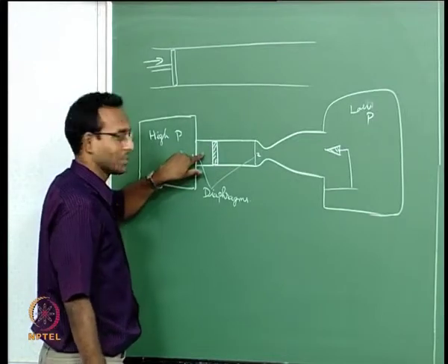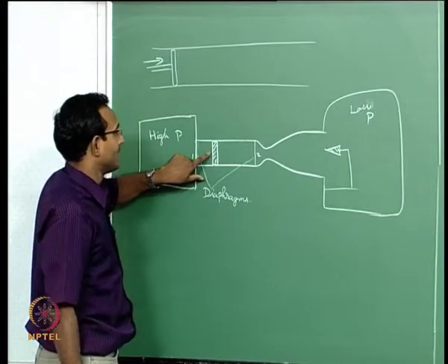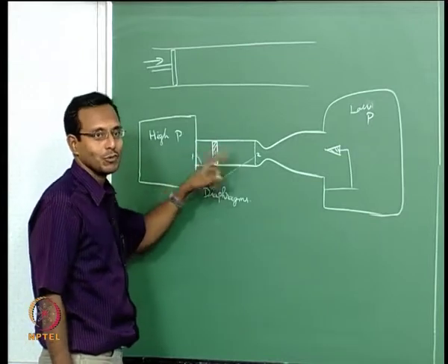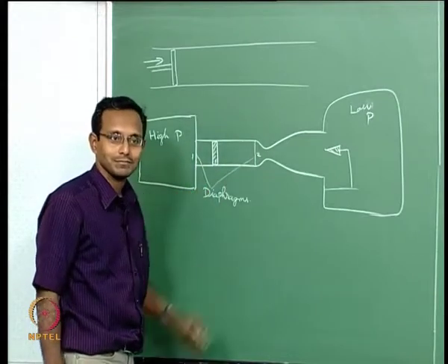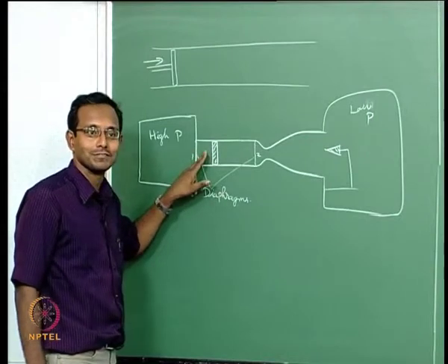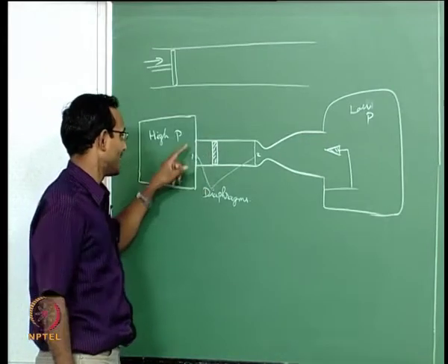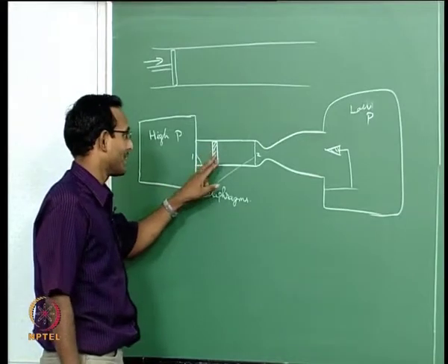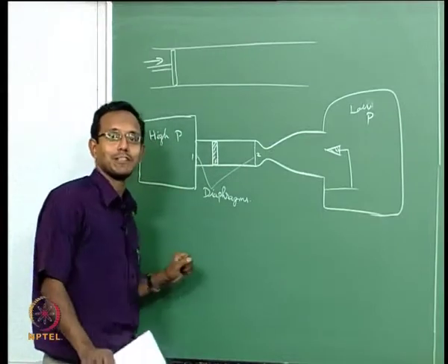I used this pressure difference to create a high pressure locally here, and then that piston moves very fast, and because of that piston moving fast, now I am going to create another shock that is going to go this way. Is this shock going to be stronger or was the original shock stronger? First one, let us say diaphragm 1 breaking, that will create a shock, and that reflected and it came back, and the lightweight piston is travelling with some velocity and that is creating a shock. Which one will be stronger is the question.